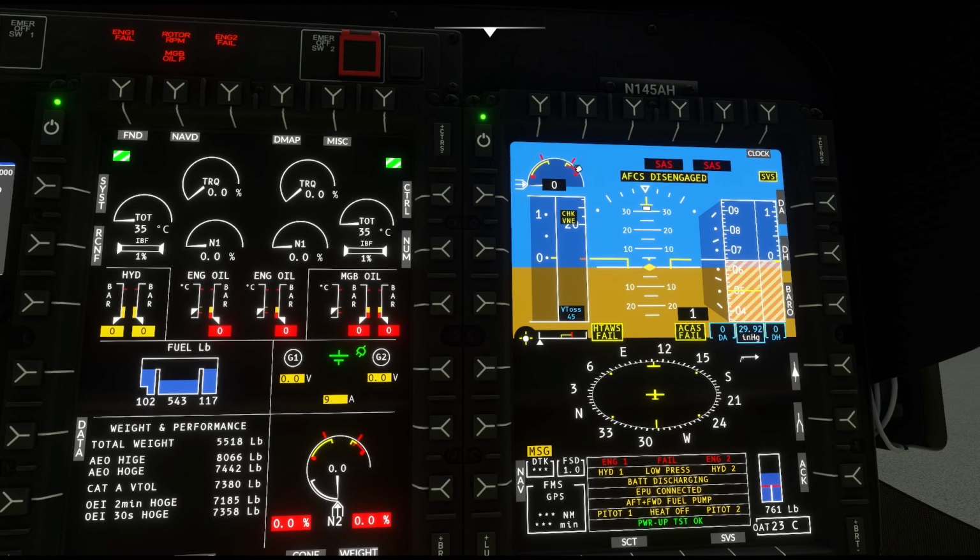This is kind of a max power off transient range. This is a power on transient range. This is a power off transient range. So if you're autorotating and you end up in here, it's not the end of the world, but you need to get it back below this red line. If you get above this in an autorotation, now you've got some maintenance you've got to do.